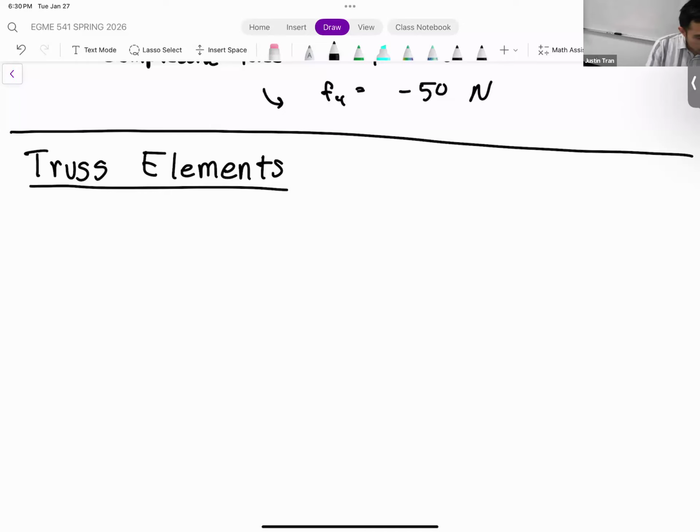So that last example that we just did was a good illustration of the finite element process. Like I mentioned earlier today, no matter what type of technique or implementation of finite element analysis you're going to be implementing, you're still going to be following the same 4 steps. You're going to be computing element stiffness matrices, assembling the global linear system, applying boundary conditions, and solving in some way or another. The only difference is basically going to be in the types of elements that you apply.